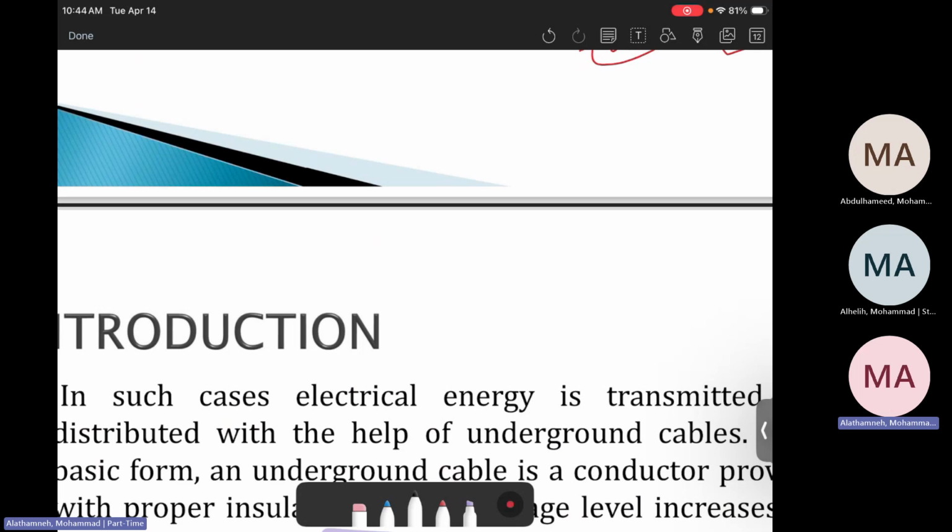The other thing, we make them underground cables because inside the cities there will sometimes be pollution, for example in industrial cities, or they're afraid of car accidents, so we don't want the poles to fall down, or there are very large buildings. And the other thing related to it is that we need to make sure the view of the city looks nice. We don't want the power lines to ruin it. So that's why inside the cities we use underground cables, especially I'm talking about medium voltage.